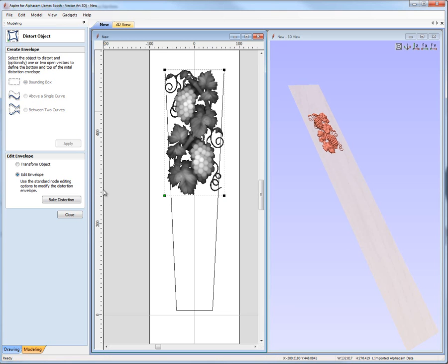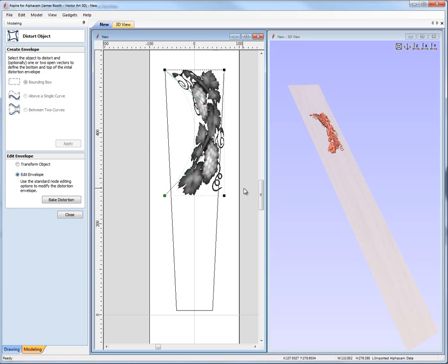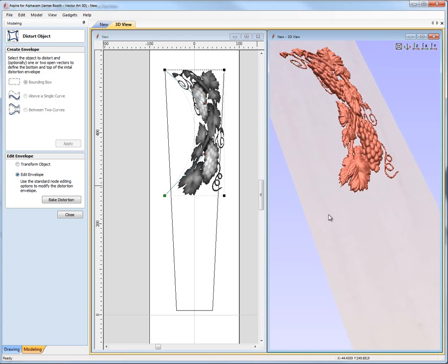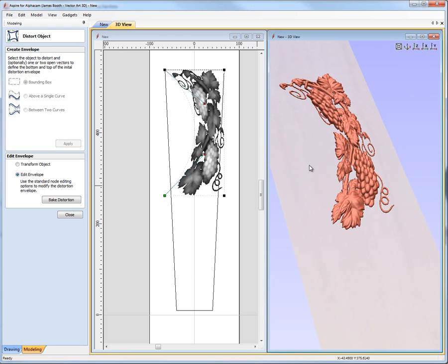First thing I would show, just to show how powerful this is, is to come over to this left hand side here, and I'm going to click on that, and then I'm going to use B with the mouse hovering over that to change that into a Bezier span. I would grab these two control points and just make a very extreme bend in that to just show people just how much you can distort an existing 3D object.